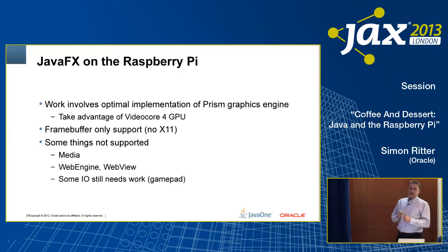One of the nice things about the Raspberry Pi is that although the processor itself is fairly slow and is not like a typical desktop, the graphics processing in it is actually quite powerful, even by today's standards. So it has a thing called a Video Core 4 GPU, and it can certainly run at sort of HDMI type resolutions, and it can do 720p, 1440p without any problem. So a lot of people use Raspberry Pis as media servers because you can drive a full TV with high resolution on it without any problem.